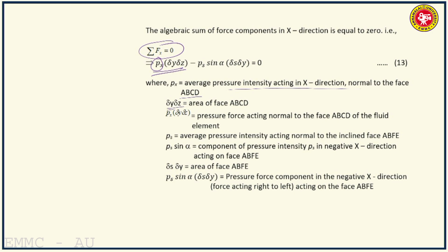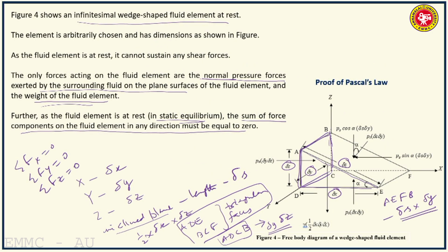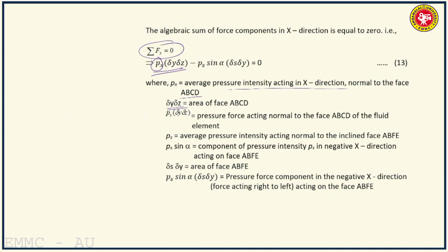Delta y delta z is the area of face ABCD. So Px delta y delta z is the pressure force acting normal to the face ABCD of the fluid element in positive x direction, that is towards right.